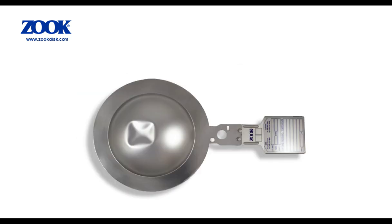Rupture discs are engineered products, but they can be delicate and fragile. Especially with reverse acting discs, any minor damage to the disc dome will negatively affect performance and cause the disc to burst or collapse low. All disc manufacturers will take extreme care to fabricate, package, and ship you their discs in good condition, but handling in the field is just as critical. Discs should always be handled by their edges or tags. Never touch the disc dome. If a disc shows any signs of damage whatsoever, it should not be installed. Consult the maker.